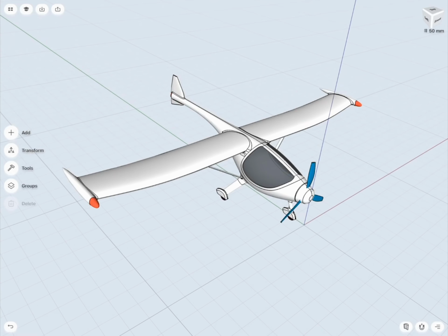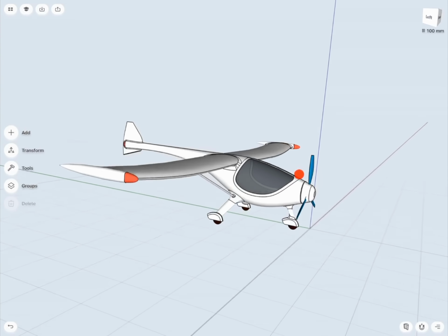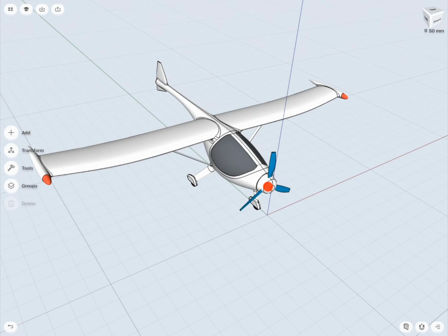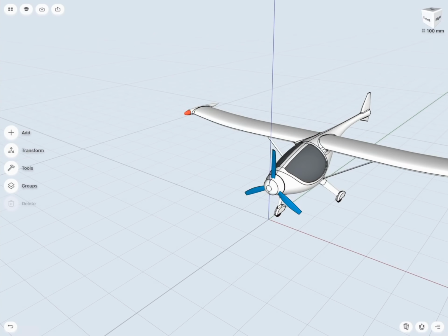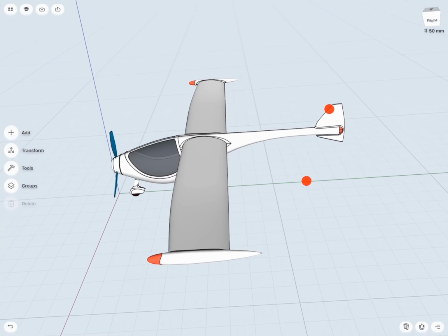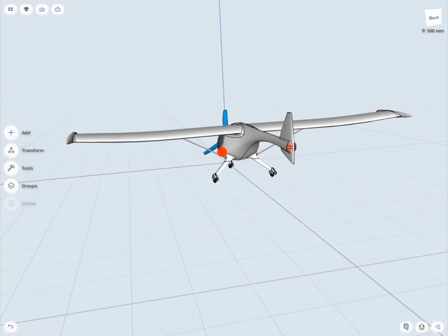We're going to set up a general shape line, and then we will create splines to use them as profiles for the Loft tool. The second stage is going to be adding details such as a plane tail, cockpit and its windows, wheels, and propeller. At this stage, we will be using various transform tools, subtract and extrude.